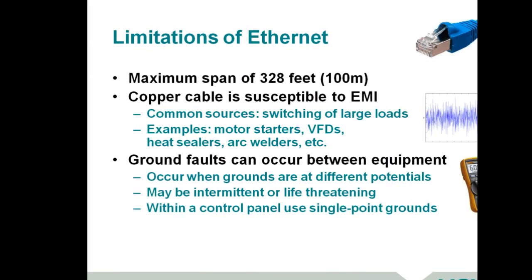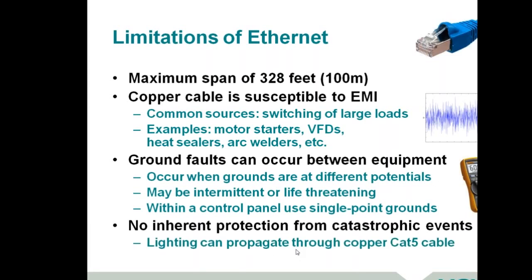Some of you who are a little experienced have maybe found that you need to be careful when plugging in test equipment or even plugging in a laptop. I know in a past life as an applications engineer, a common thing was that if you weren't careful, you'd take out the ports on your laptop, and that's simply because the current's trying to find a quick path to ground. And lastly, there can be certain situations where you have a catastrophic event, something like lightning, in terms of a building or a remote application.